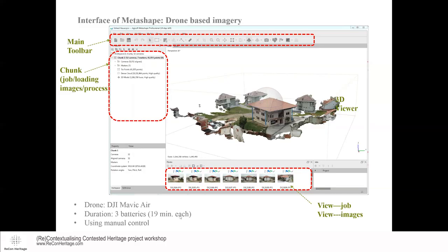These were captured on a drone, so with 3 batteries, you can get nearly an hour's worth of flight time to capture images. I think the person who took these photos didn't use all 3 batteries, but yeah, drone photos, 52 photos. For this one, if I wanted more detail, I would probably have done around 150 to 200 images at least. But 52 does get you a basic model.